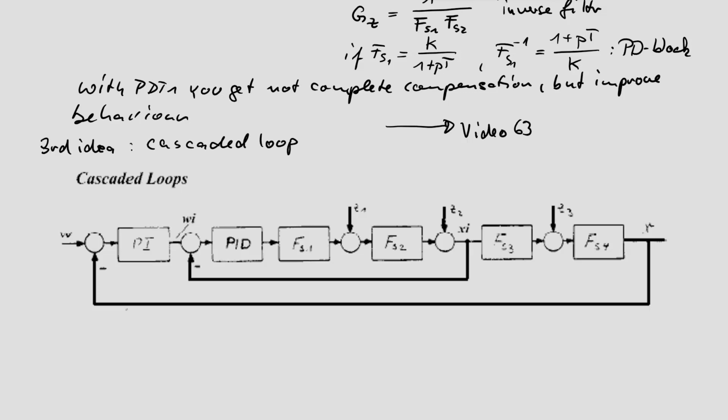So it is not just added in series connection, but with an internal new feedback. That is new. So we have an internal loop and an external loop. Now we have a two-loop system, and that is called a cascaded loop. The cascading principle: an internal loop, influenced by the output of the outside controller, influenced by the controlled output X.